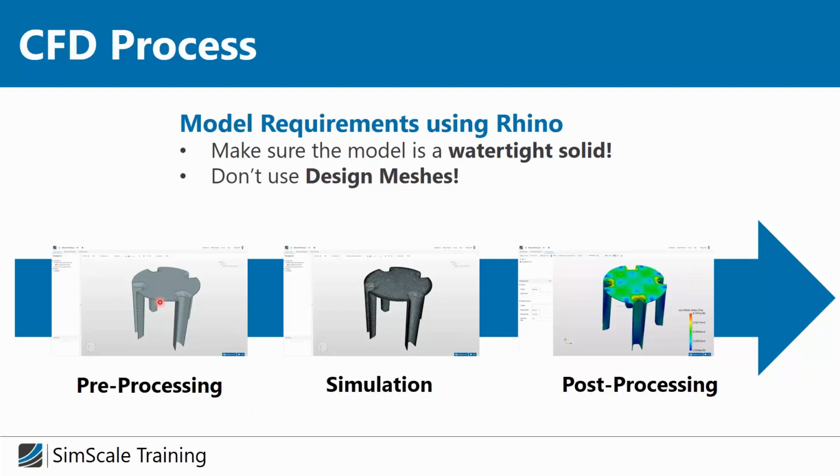simulation of a chair. And what we have to do therefore is first of all to prepare the geometry, our CAD model for simulation. And this is what Roddy will show you in a couple of minutes, and how to prepare your geometry for a simulation in Rhino. Then I will show you how to set up the simulation, which means create the mesh, so divide this model into the small finite elements, how to set up the simulation, analyze the results. Okay, so now I would like to give the word to Roddy.